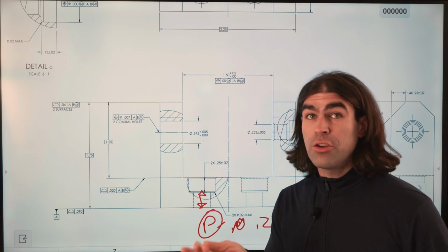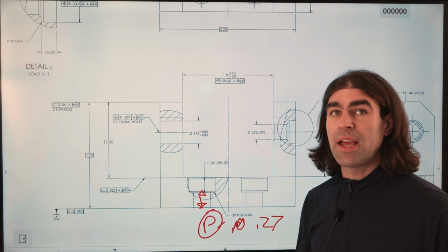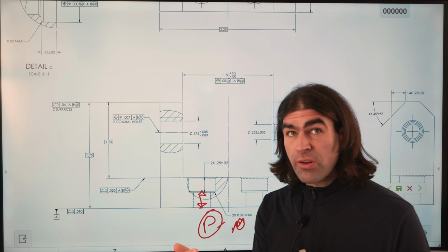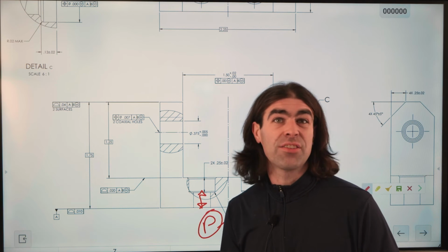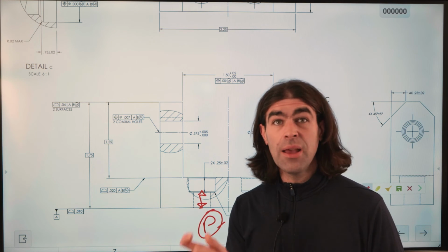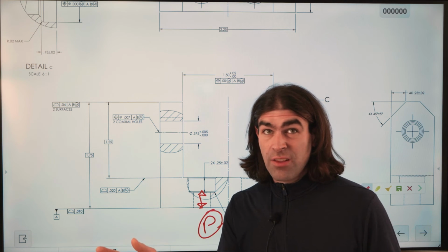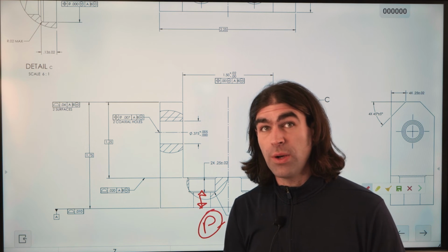Okay, and then you could look at that in your tolerance stack up as well and see if you got enough room with that counter bore. You might have to take into account this whole area. The longer the projected tolerance zone is, the more difficult it is to manufacture and inspect. 1/4 inch is a good distance. The little thread plug gauges that are commonly available usually aren't that long, so 1/4 inch is easy enough for manufacturing and inspection to deal with.